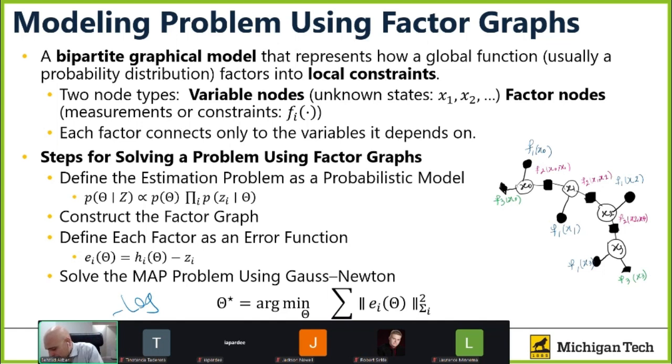For example, you are designing a robot that just deals with an IMU sensor, just gives you odometry, just counts, for example, the steps of the movements of, I don't know, the wheels. We have a wheel sensor to measure that. And later you want to have GPS too, to get direct measurements.